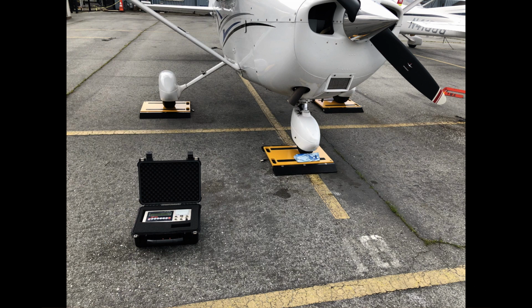Scale preparation. Mechanical and electronic scales shall be inspected prior to use and set to zero. This is done by adding and removing a weight, then rechecking for zero. This process should be repeated until a steady zero setting is obtained. The scales should be located in the same environment in which they are to be used and allowed to come up to temperature at least 2 hours prior to use.